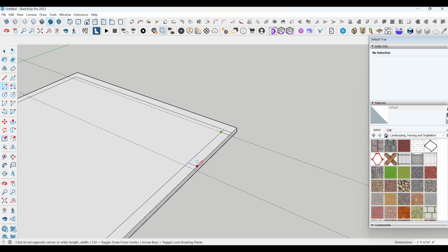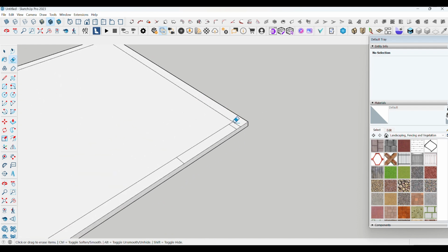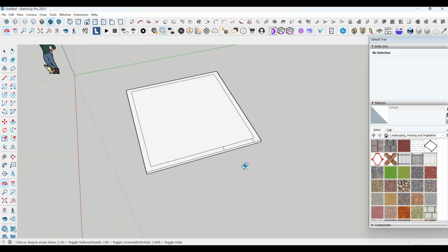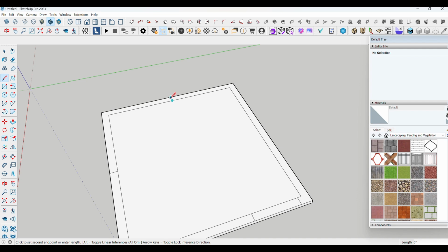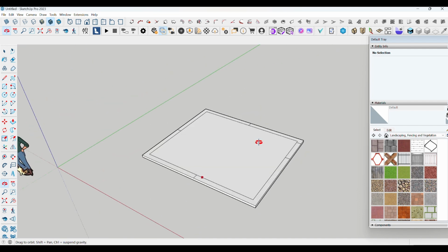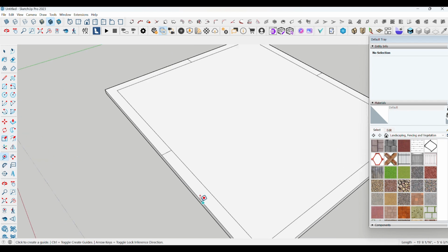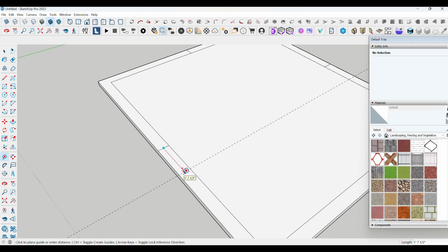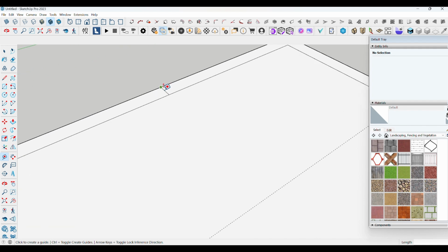Now just create a rectangle over there to extrude, and erase whatever tape measurement lines we made for reference. Next to that, here we have to take the window. You will get the default midpoint for the window. After that you have to create a window, selecting the size accordingly. I'm going to take a 3 by 4 window. I'll give the tape measurement of 1.5 feet on both sides. I'll repeat the same procedure for every window. So let's do that. Here 1.5 feet.